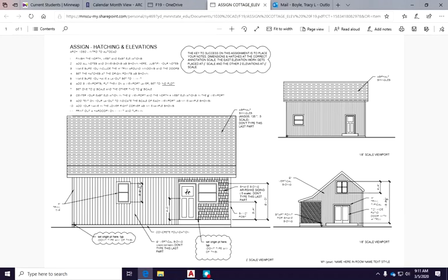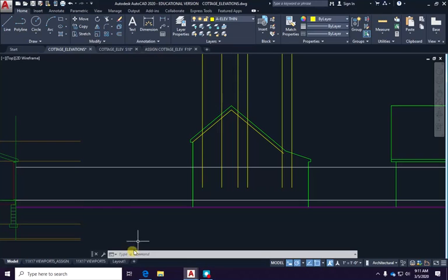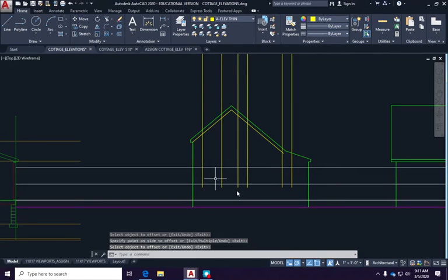And then I'm going to come down right here because my windows are 3'6" deep or tall. So we went up 6'10", down 3'6", which is the equivalent of down here. I've got another dimension that says 3'4". Gets you in the same place. All right, so I'm going to go back over here, offset 42, which is the same as 3'6", and now I have a rectangle, or I have the ability to create 3 rectangles.